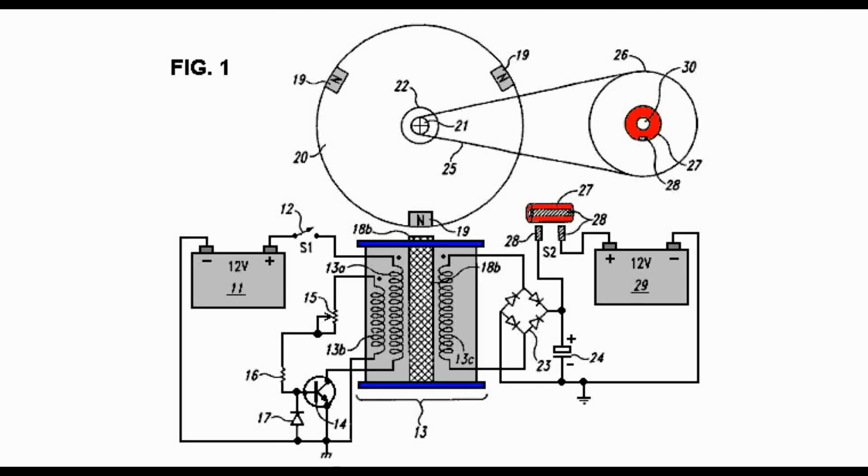The poles 19ABC, which are actually permanent magnets with their north pole facing outward from the rotor 20, maintain the same polarity when in momentary alignment with pole piece 18B. Rotor 20 is attached to rotor shaft 21, which has drive pulley 22. Attached to rotor shaft 21 are rotor shaft bearing blocks 31A and 31B, as seen in Figure 2.